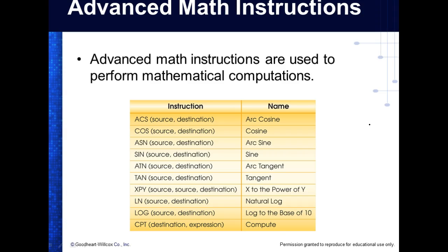So what they're starting to do is put counters back in these PLCs. I mean, we're talking about hard counters. They're actually inside the chip, and they refer to them as high-speed counters. So the 1100 has a high-speed counter in it, which means it doesn't take up any lines because the counter's there. All you do is specify what to load that counter with. If you put a counter instruction in your program, it is literally running a program that simulates a counter. If it's got a high-speed counter, then by George, there is a true counter inside that thing.